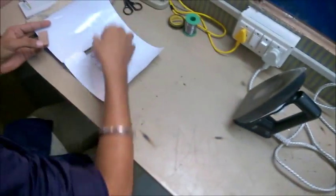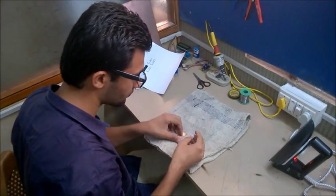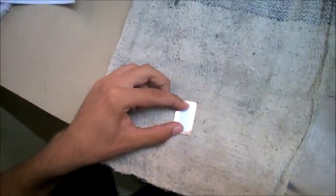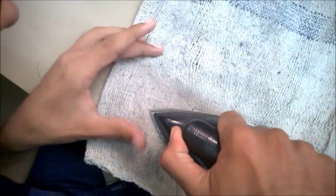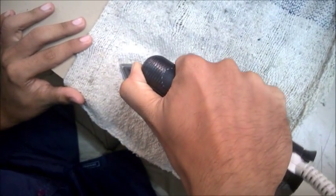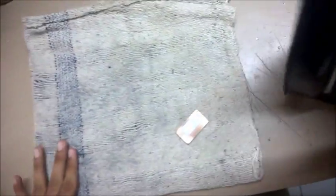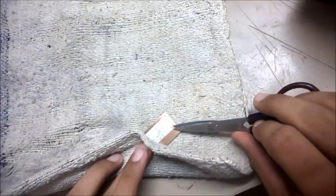Now after that you will need an iron to iron it. Keep this printout on the PCB and take the iron and keep it on it in such a way that it doesn't move. It keeps steady on that PCB. It will take around 2 to 3 minutes to iron. Take care while removing this because currently it is very hot.